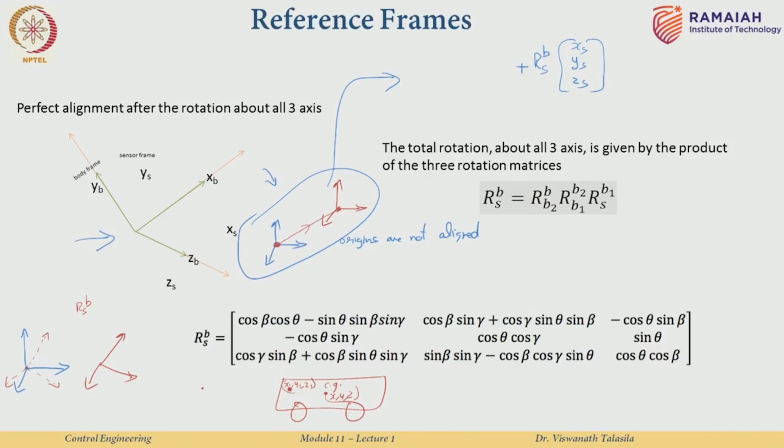Subtract out those differences, and all you need to do is to add that small difference. So, I will call it x difference in the translation position, y difference in the translation position, z difference in the translation position. If you add this to the rotated values, you are going to get perfectly xb, yb, zb. So, first take care of the rotation between the two axes, then align the origins. Done. You are essentially done with 3-dimensional inertial navigation.